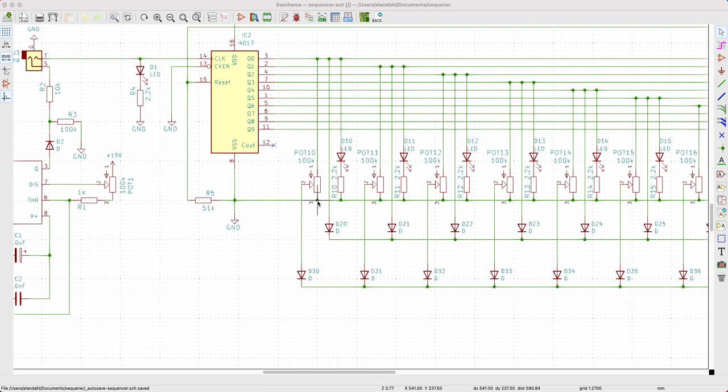If you want to put a wire on the diagram, you use the green wire line. If you want to force there to be a dot connection, if KiCad doesn't figure it out on its own, you grab and stick one down with the node tool over here.